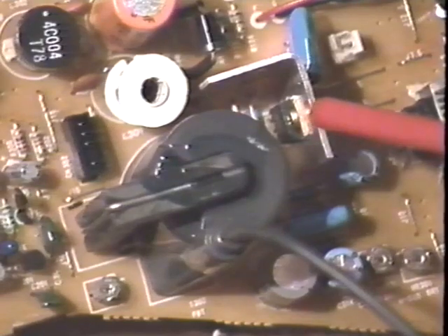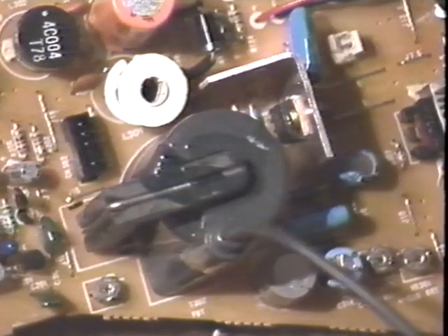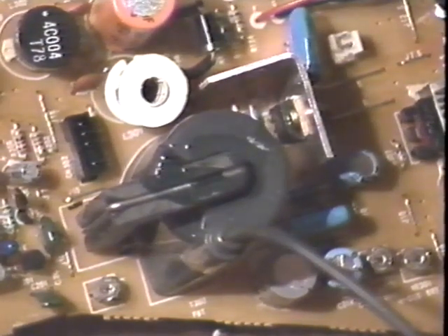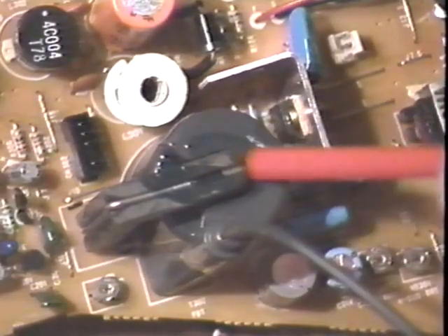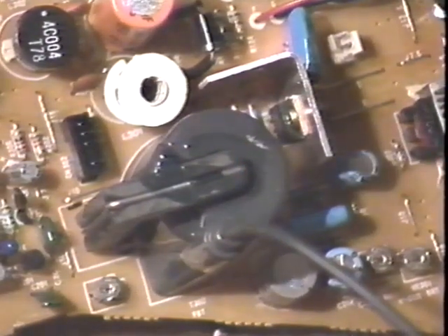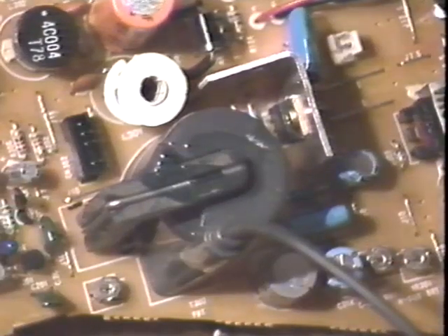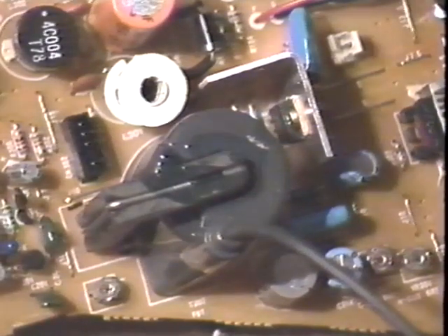Most monitors use the output of the horizontal circuit to do more than drive the horizontal yoke. The pulses are applied to a flyback transformer, which produces extremely high voltage, low current supplies needed to bias the CRT elements. As with the horizontal output transistor, do not touch the flyback while servicing the unit.